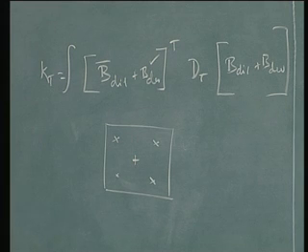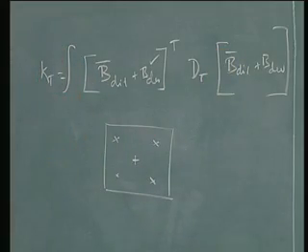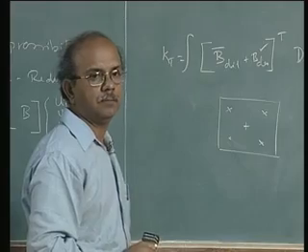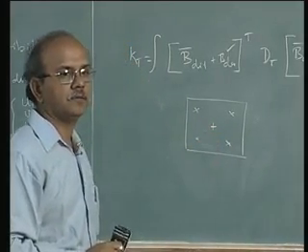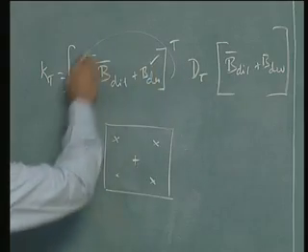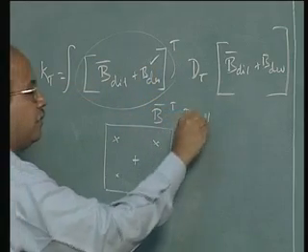This is the standard procedure of Hughes. So this and this part, both of them are evaluated at, say, a single Gauss point. Many people together call this the B bar method. So B bar transpose D B bar and so on.